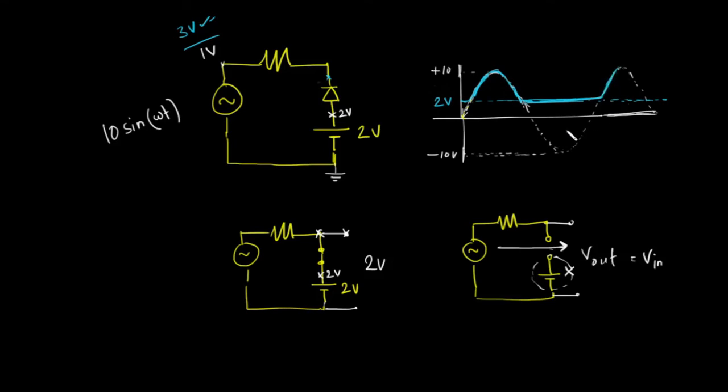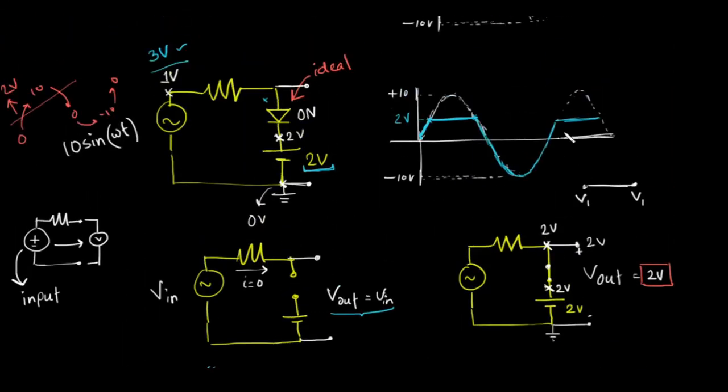So since for 3 volt it remains off, the diode will remain on for all voltages that are less than the anode voltage, and for all voltages greater than the anode voltage, the diode will remain off. Okay, if the cathode voltage is greater than the anode voltage, the diode will remain off. If the diode remains off, then the input voltage will pass exactly to the output, and well, yeah, that's about it. So this is how the clipper configuration works.